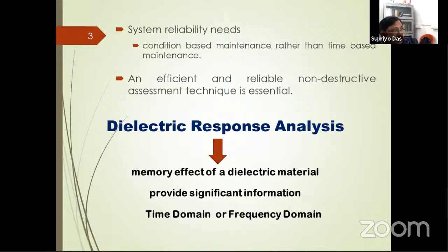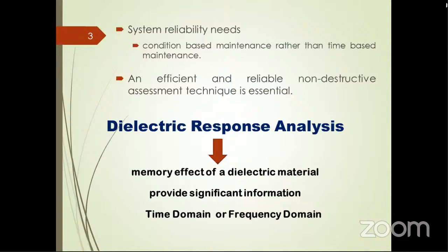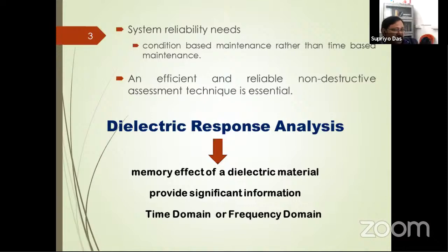That means what is the situation of the dielectric, or what is the change in the characteristics of the dielectrics. Those things we can identify using dielectric response analysis. This analysis provides significant information about the dielectric material. We can carry out this in both time domain as well as frequency domain.